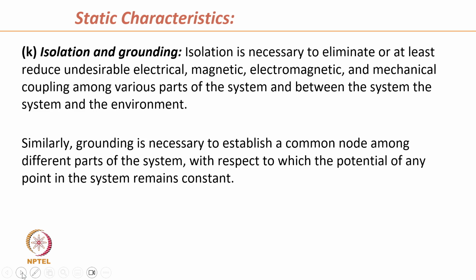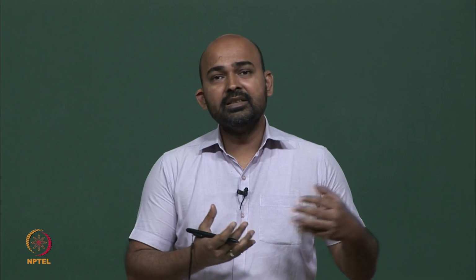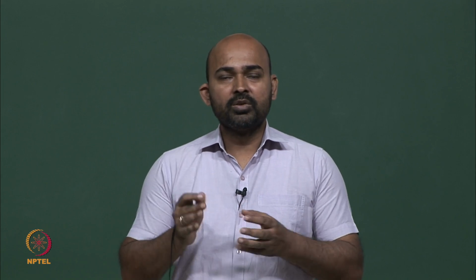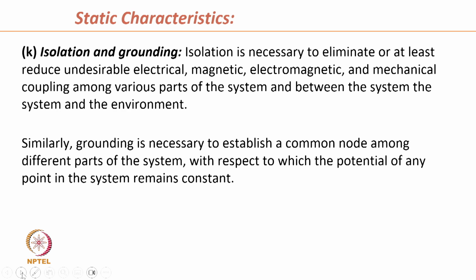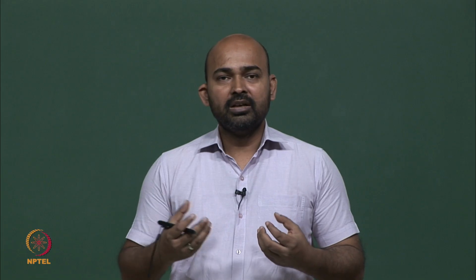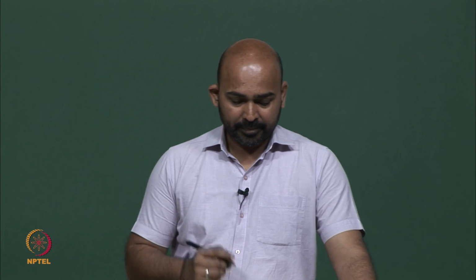The sensor should not be exposed to this 12 volt, because if 12 volt comes in, the sensor can be damaged. So there should be isolation between the sensor and electronics. However, the data should flow from sensor to electronics. It means the AC signal, the data, should flow, but the DC voltage should be blocked. So we use decoupling capacitors between these two blocks so that the DC voltages are isolated, however, the AC signal can flow.